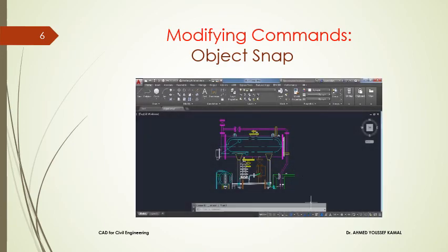Now let's look at some of the other points which are indicated in this object snap. The next point is node, which is a point. In order to snap to a point object, you need to turn node on. So let's type POINT and press enter, and let's make some points. So here we have a point.